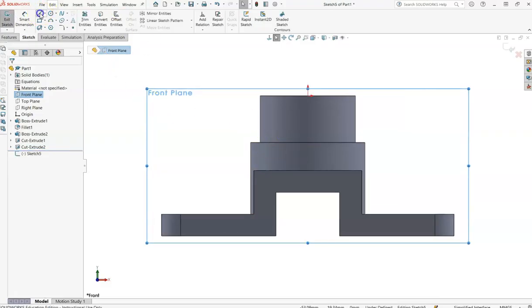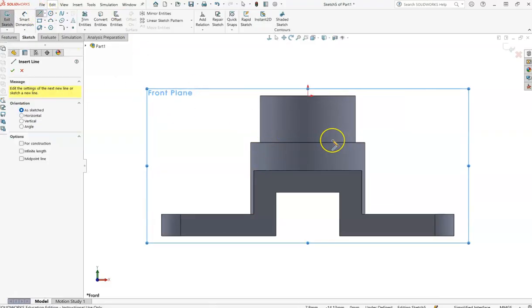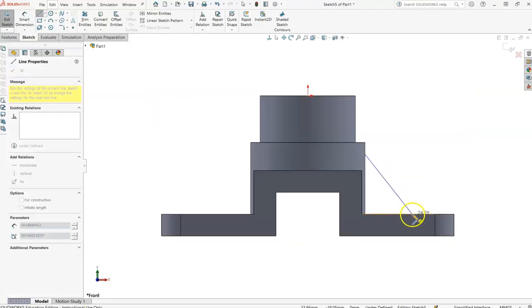And you're going to just draw one rib at a time, and you can mirror this across then. It doesn't let you do both for some reason. So I'm going to get my line tool, and I'm just going to click on this line and then down here. Now you want to be careful when you're moving down to this line that you don't click on that midpoint, you don't click on this point. I know sometimes the center point of the circle pops up, there it is. You just want to be on that line itself.